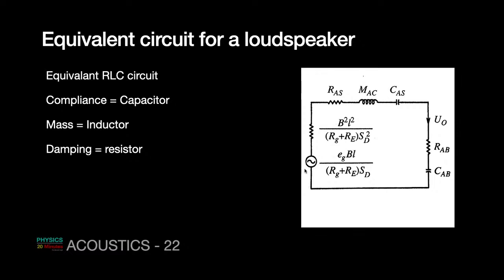You can drive it by an AC signal, which is equivalent to a signal that drives the speaker. And once you run your algorithm, your calculation, you are all well familiar with the LCR series circuit. They give a resonance curve at a particular frequency, and the particular Q value can be calculated. So this is typically the circuit which is used to practically or theoretically simulate real speakers.